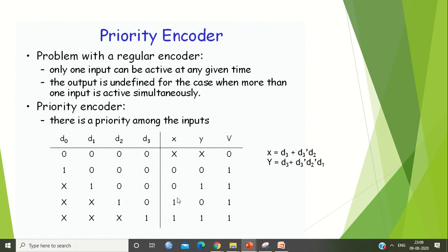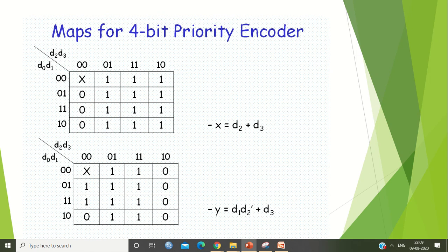Here you can take this X and X. This can have 2 values, 00 to 11, so 001, 011, 101 and 111, all the values along with the 0 can be appended. So here another 4 values, totally 12 ones will be there. You can group these 8 into one thing, and the other 8 into another, so the expression is D2 plus D3.